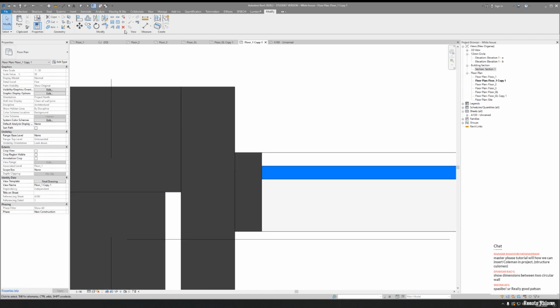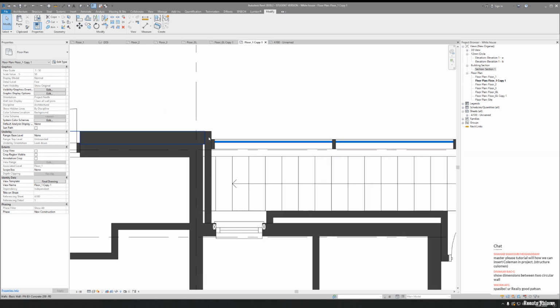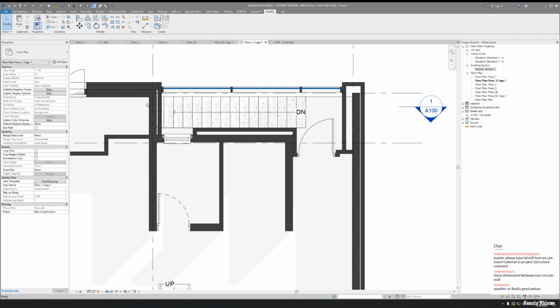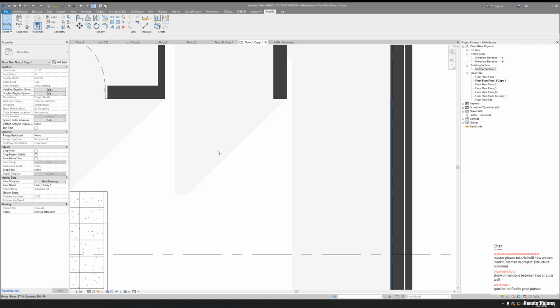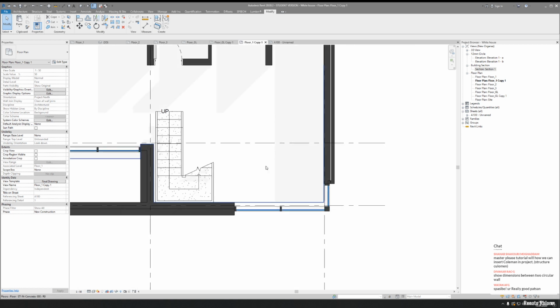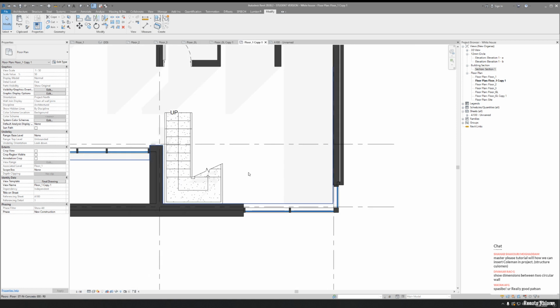I will join it. And as you can see, here is the gap line. I don't like it. You can do the same thing with invisible lines, but you will get a white line. So this happens when you're trying to hide the lines inside some object. If you do that inside some object, you will get the white line, because this hides everything under this line. Okay, so we did that.